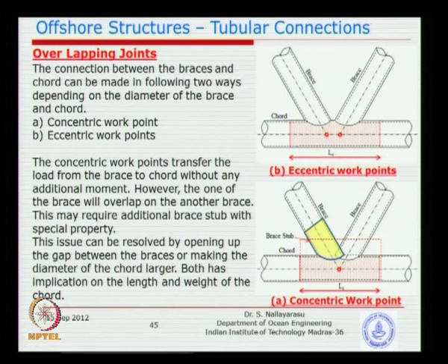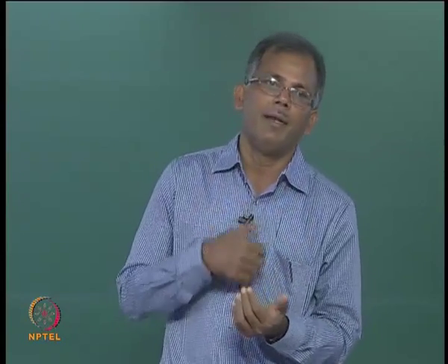So, actually you are not going to save too much, it is only a perception that you do an overlap joint, I will try to save this much, but ultimately the design becomes complicated, and you also have to spend some more material in compensating, because after all, if this does not have a special property, that will fail. So, that is why normally not recommended.